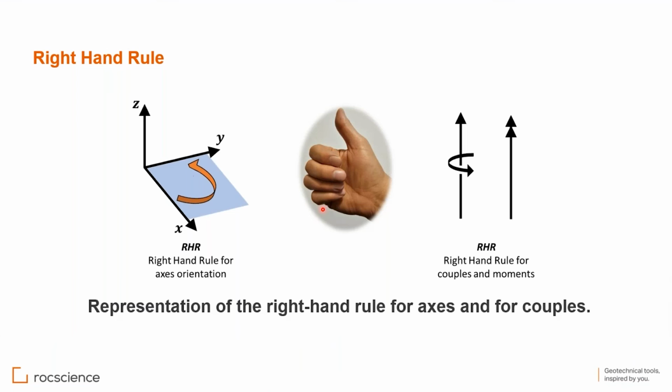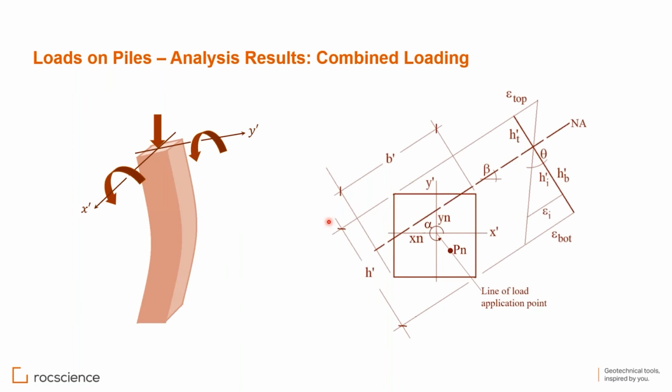So in structural design, you need to remember that you have specific direction of load application. So you remember the right hand rule to apply the moments positive and negative, and the loads you apply are always in the global axis directions, not in the local, because you can rotate the pile in the local coordinates, but the global coordinates of the project will remain the same.